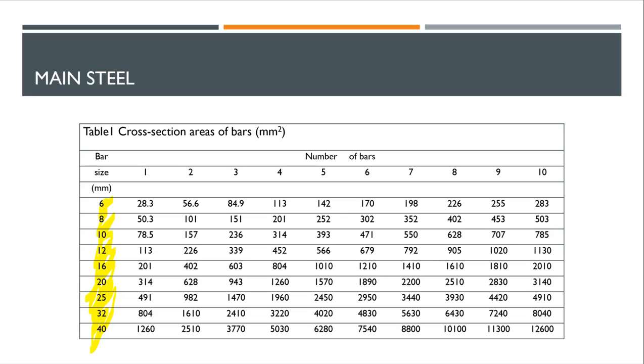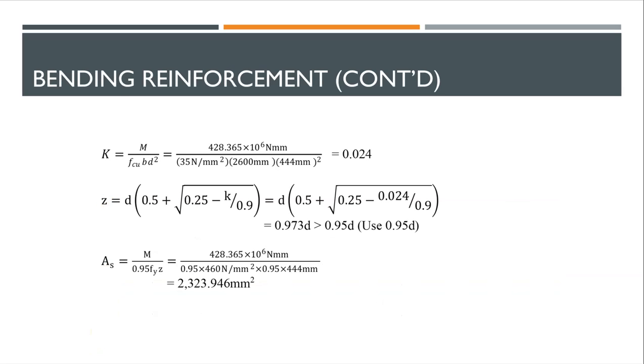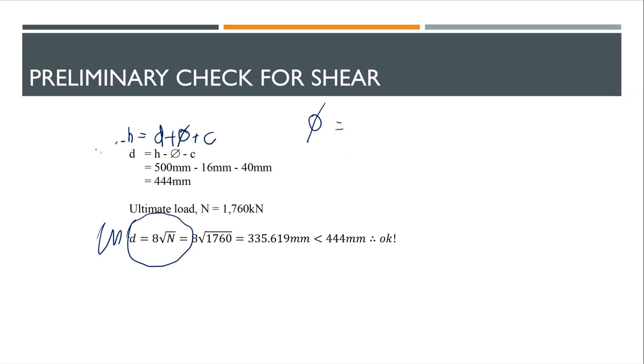We worry that the bars are too far apart, which will cause cracking and such, which will cause a serious fatal problem later on. That is what we worry about. So we won't take sizes that are too big. Basically what we always assume is 16 to 20 like that. For foundation, for pad footing, don't confuse it with different types of footing, because what we learn today is pad footing only.